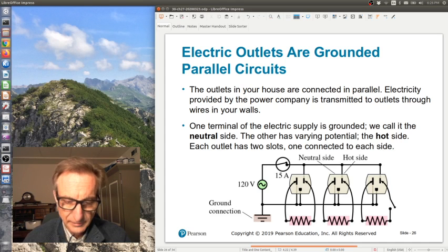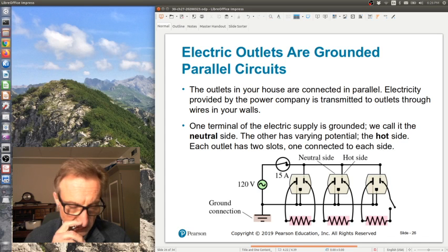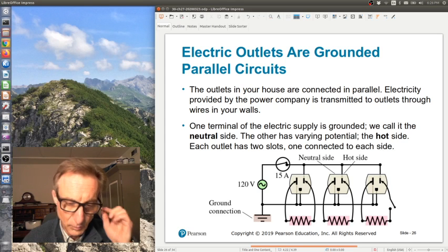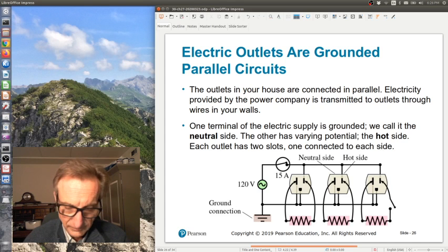Any individual circuit breaker either feeds one outlet or a few outlets, or one of a few devices, for example, a light in the ceiling with a switch on the wall. There are several circuit breakers in that panel, and the total current coming into the house can be something like 120 amps, but each individual collection of circuits has its own circuit breaker to make sure that no circuit draws more current than it should for safety reasons.